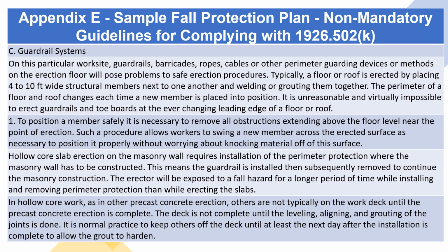In hollow core work, as in other precast concrete erection, others are not typically on the work deck until the precast concrete erection is complete. The deck is not complete until the leveling, aligning, and grouting of the joints is done. It is normal practice to keep others off the deck until at least the next day after the installation is complete to allow the grout to harden.